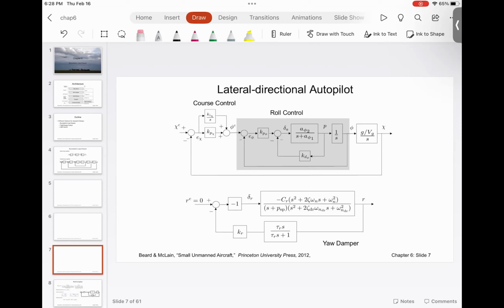But as soon as the transfer function is in the form of spring, mass, and damper, you can control the behavior of that system. And I know all of you know this, but for my own satisfaction, I'm going to write this down, because here is what's going to happen. Once you linearize, this is the beauty of this approach. Once you linearize, and then you treat all the non-linearity as a disturbance, and once you combine all these transfer functions into one big transfer function, that transfer function will look very similar to a spring mass damper transfer function.